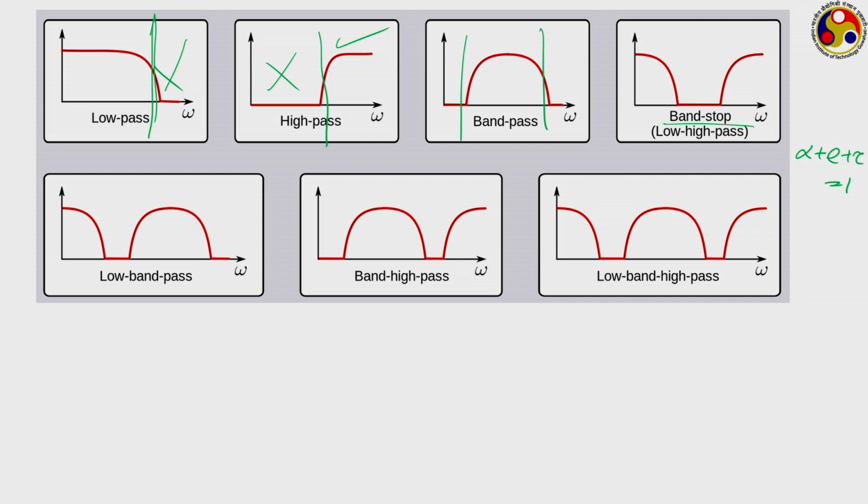For a perfectly black surface, we generally have alpha equal to epsilon, which is called Kirchhoff's law, that is, emissivity and absorptivity are equal. For practical surfaces, like an opaque surface, tau is equal to 0, so that alpha plus rho is equal to 1. But the values of both alpha and rho vary with the wavelength. So, depending on which wavelengths we are going to talk about, accordingly we can select different kinds of filters.